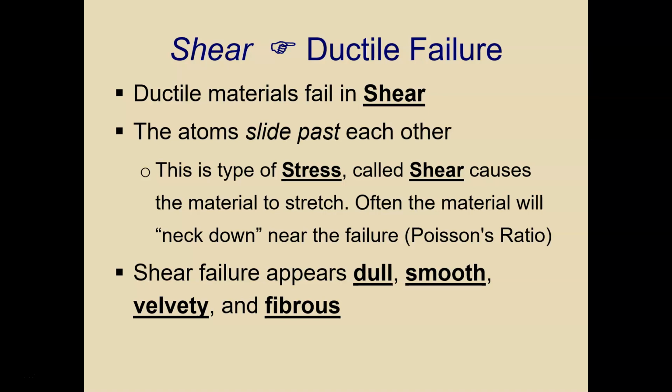In ductile failure, the crack grows at a slow pace and is accompanied with a great deal of plastic deformation. In this case, the crack does not expand except when high levels of stress are present. In almost all material design situations, materials that exhibit ductile failures or fractures are preferred for various reasons, such as ductile materials deform plastically, slowing the fracturing process and allowing more time to correct the problems so they can see it as it's happening. Higher amounts of strain energy are required to deform a ductile material.